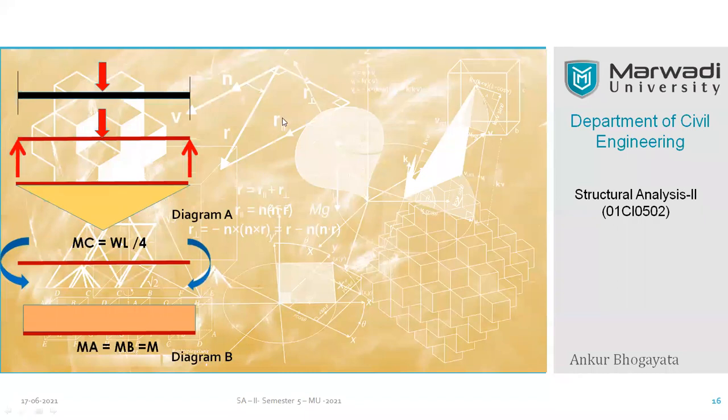So now our actual step starts. See, we have already performed this segregation. We have done the analysis by and large. This is your point load. This is your moment. So because of that, we have all the important ordinate values. Here, the value of the BM diagram due to the point load is WL by 4, where L is to be assumed as the complete length of this beam, right? And W is the load here. Right? So this is a W load and L is the length.